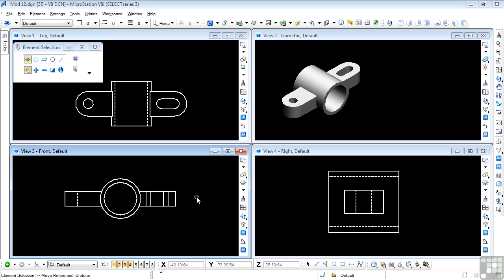The next step is to add some section views, which is a little more difficult to add to the sheet model. There are several ways this can be done, but the basic requirements for a section are that it should be self-updating, in other words, dynamically linked, and hidden lines should be displayed. Now, the three methods I'm going to show you all work exactly that way, but sometimes you have to make a few compromises. The first method we'll talk about right now is called the fence clip.